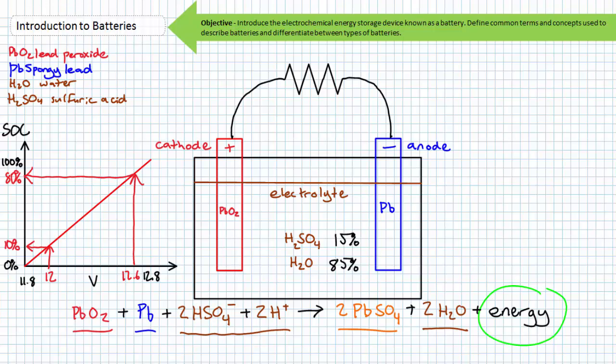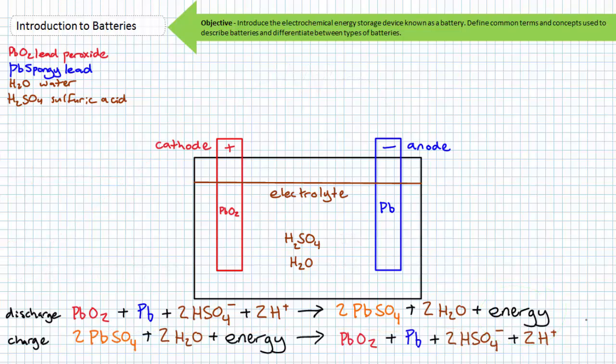If we scale this same curve to a nominal 6-volt battery, we realize our previous open circuit voltage reading of 5.95 volts is actually an indicator that this battery is in pretty rough shape and essentially running on empty. Flooded lead-acid batteries are a type of secondary battery and can be recharged. Charging a battery is essentially the reverse of discharge. During the charge process, conventional current is forced into our previously labeled cathode, or using electron flow theory, electrons are forced into the previously labeled anode.